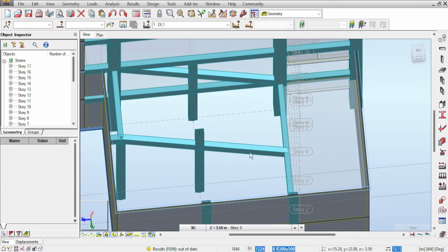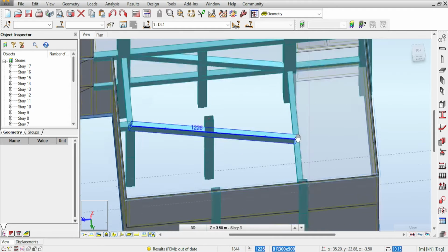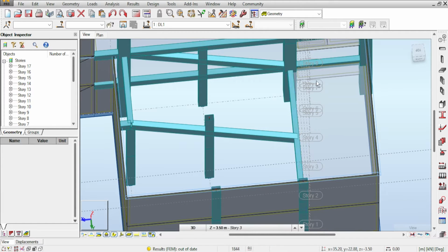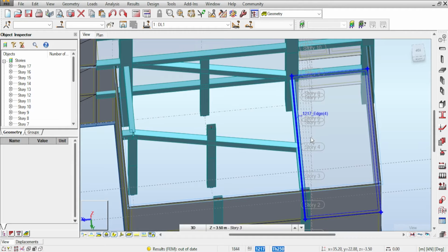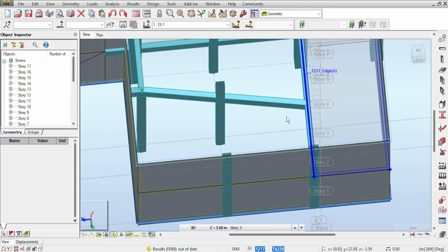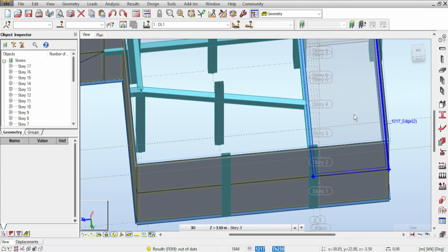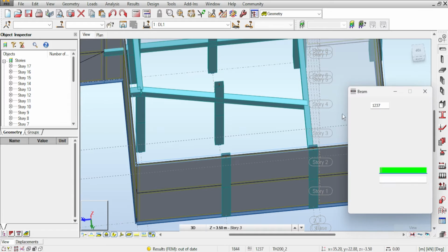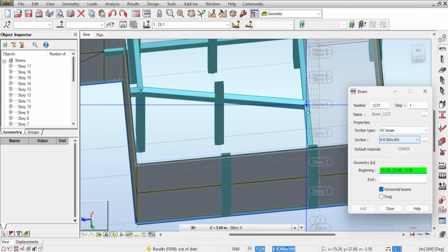Okay, now here I had some comments from you that it's very hard to maneuver. So I'm trying to help. I agree, first of all, this is a very small space to maneuver a car, and I 100% agree. But I'm trying to somehow make it easier, although I disagree with the dimensions and I should talk to my architect on that point. I will try to make it easier by making one slope and one horizontal, just to make turning around easier here. I'm just trying to salvage whatever the architect gave me. I don't necessarily agree with this, but it might salvage the entire issue.